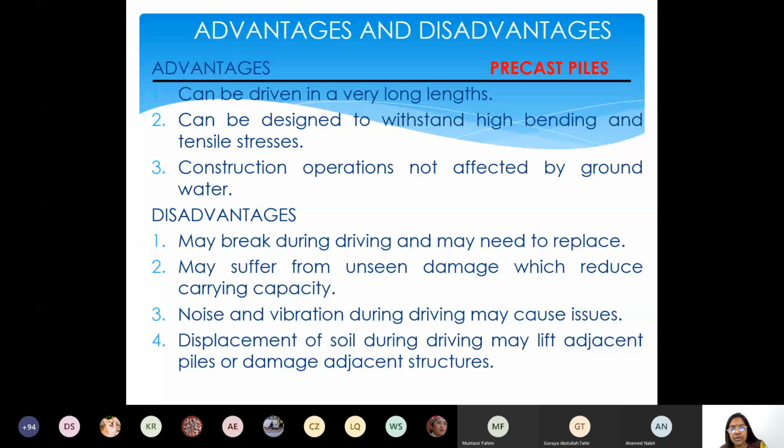It may be crossing by, but you will still be driving the pile into the rock surface. You're not reaching the water surface. You will be passing by and then reach the rock surface. So you're safe from groundwater interruptions or any moisture changes in the foundation resulting in any settlement or differential settlement of the building, right?